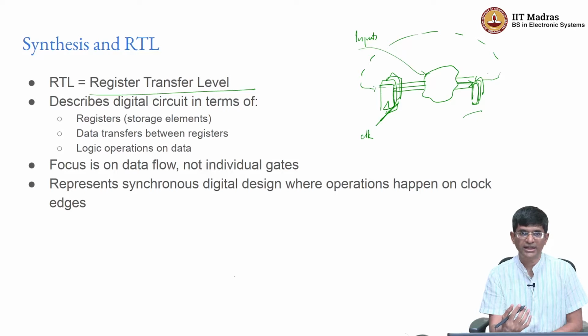It is important that you be able to think in terms of what your design is doing at the register transfer level. What that means is you should be able to break whatever design you want down into a set of storage elements where some values are being stored, and some computations which work on those values, perform some kind of complex computations and derive new values that are then going to be stored in those storage locations. The storage could also be coming from memory, or from other registers. The computations in general are combinational logic.